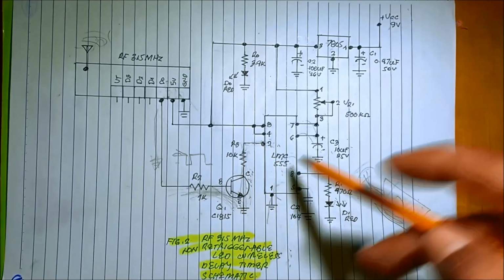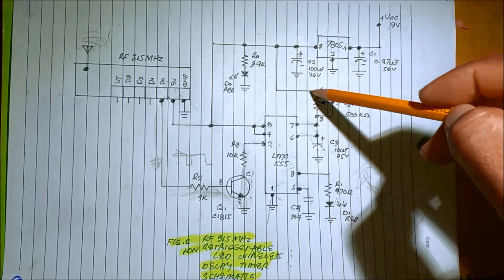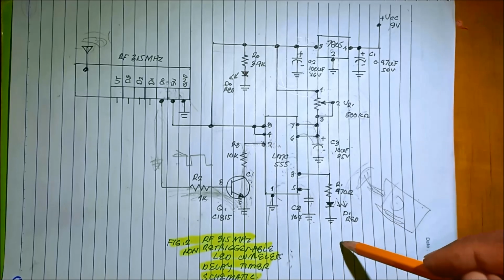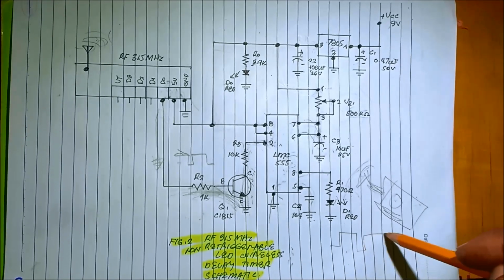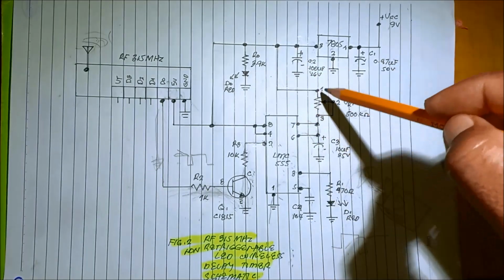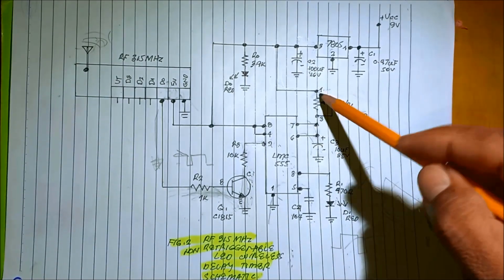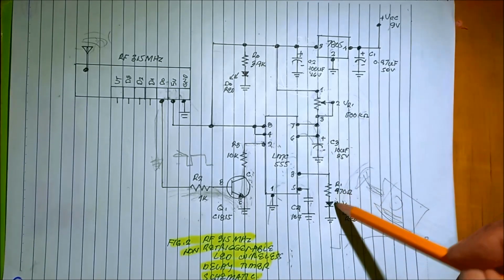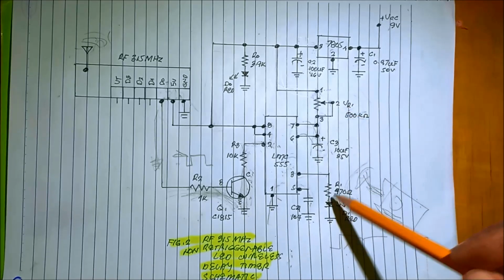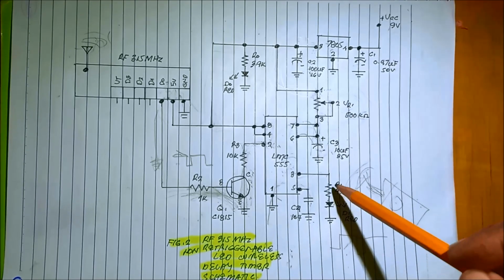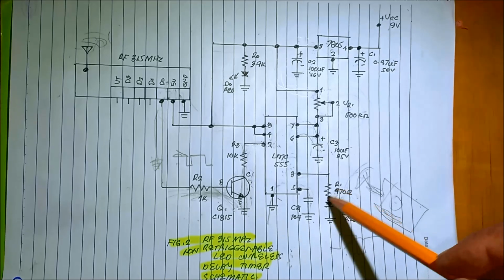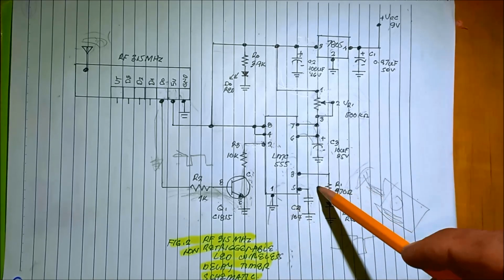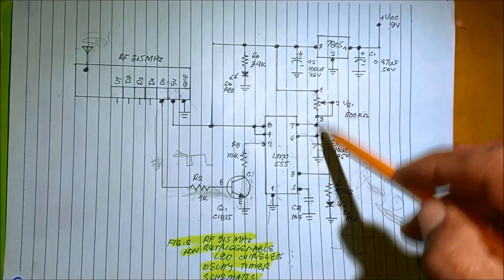What happens is, when we have this triggering base current to the transistor, it will switch on the transistor, and now the capacitor starts to charge. The LED is now on, for a certain period, because the current flows through the resistor into the capacitor. The values of the resistor and the capacitor are what determine how long the LED turns on, the delay time. How much time will this LED still be turning on? It depends on the charging of the capacitor and the resistor.